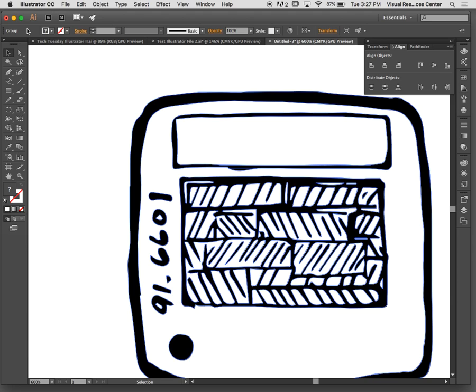When you apply live trace, you can even apply it to a photograph and it will simplify your lines, and you can keep simplifying and simplifying. There are also ways you can remove points on the path manually or in sections. Like if you have a line drawing, you can select a section and then simplify it, and you can give it some clues on how many points, like your tolerance for the distance. Change the number, yeah. The same thing is probably happening as on my drawing, that it recognizes a fill. It might be worth changing it into a black and white logo or something that will simplify it further. Maybe one of those filters in the live trace.